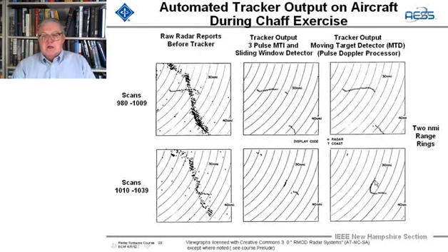And here we see with the moving target detector, a nice clear track. And right up here we had 2 detections, which were probably a bunch of the chaff cloud that didn't disperse. But remember, that's 30 scans of data over a 30 by 30 mile region, and only 2 false track points, and really clear detection of the target. And in this case, we've got 2-mile range rings. So we're actually looking probably 15 miles by 15 miles.